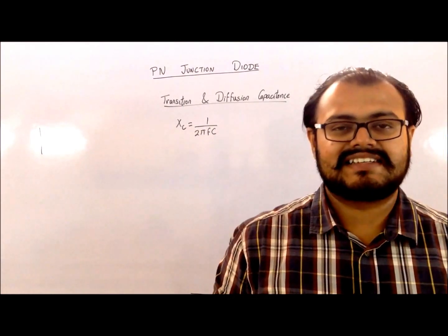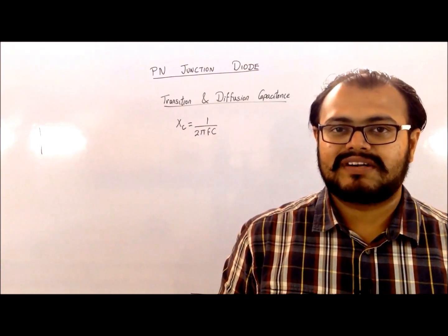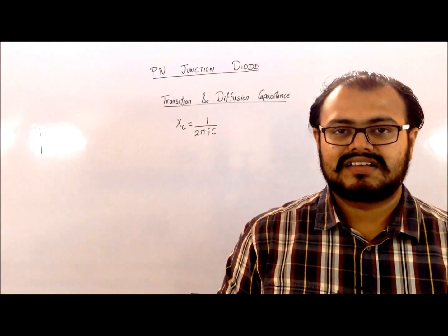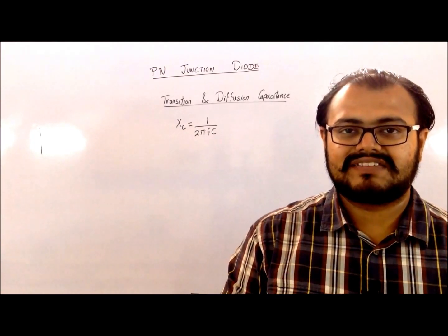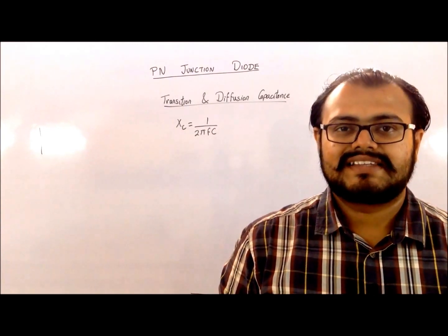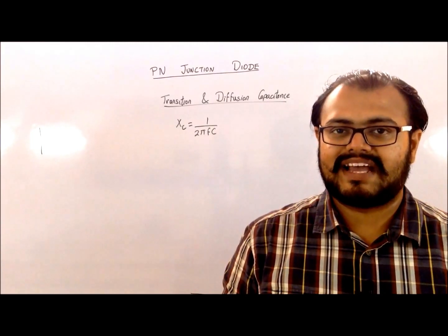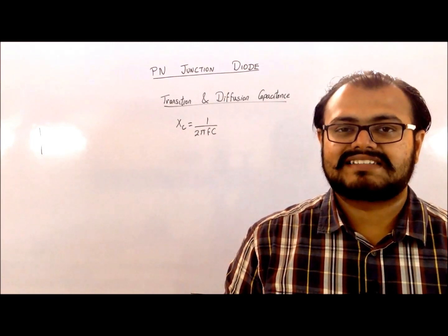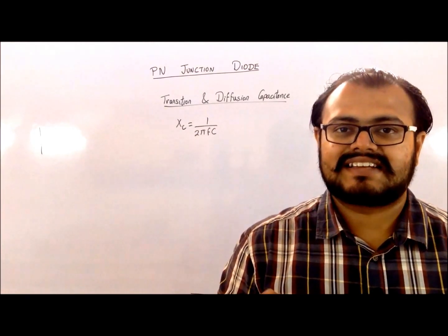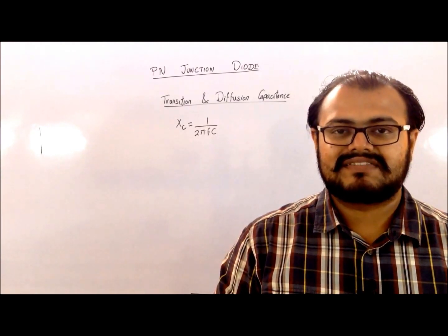Even if we consider the resistance of a normal resistor, it will also vary according to the frequency applied to that resistance. For the ranges of low frequency to mid frequency, the resistance value will be stationary in nature. It will have a fixed value. But as the frequency increases, because of the stray capacitance and stray inductance, it will have an increase in its impedance value.